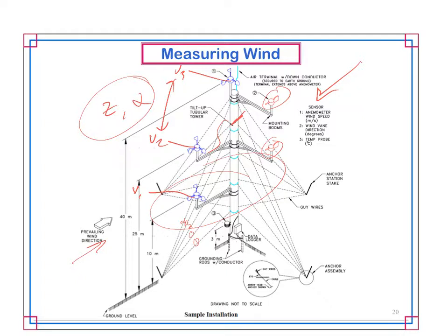on the farm based on its location. You have a data logger here that's recording all this information, and the last little important thing, well, I guess not last, because you have a lightning device, not a lightning arrestor, that actually is designed to take the hit. So if there's lightning in the area, let the conductor take the hit. As long as it's not too hard of a hit, it can take the lightning hit. It's only for a very brief amount of time, so it's the tallest thing around. It takes the hit, it directs the energy down to ground, and then no big deal. Nothing blows up. I mean, these are designed to take care of that all the time. No big deal.